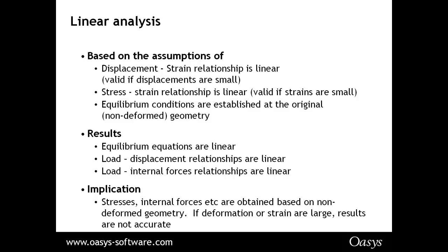The thing to remember is that because everything's based on the original non-deformed geometry, if the deformation and strains are large, then the results will not be accurate. You'll get results, but they won't necessarily be accurate results.